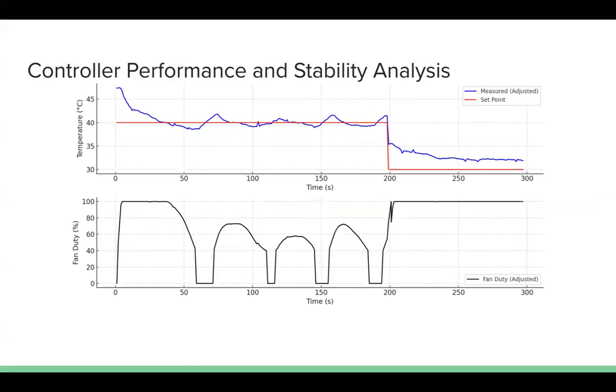We first ramped up the TC Lab for a couple minutes beforehand in order to increase the temperature, and then once we started our controller, the temperature was able to decrease first to our set point of 40 degrees, and then gradually start to approach our set point of 30 degrees after about 3.5 minutes.